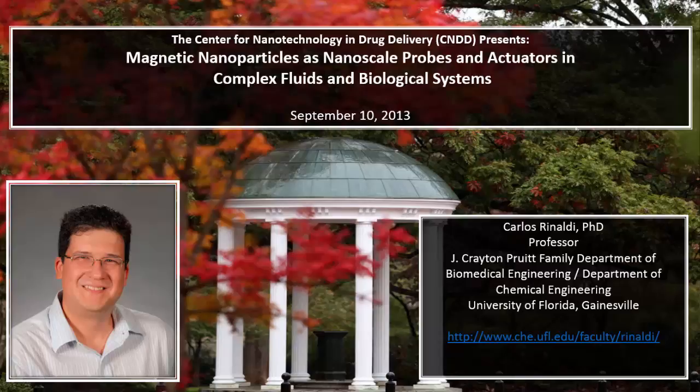You can make this quantitative, and this shows work that we've done, reported in Soft Matter, where we used oleic acid-coated cobalt ferrite particles. The nice thing about cobalt ferrite is that at room temperature, it responds to an oscillating magnetic field by physically rotating. We determined the hydrodynamic size distribution in a reference fluid, in this case hexane. We fit that to a log normal size distribution, and then we suspended the particles in a test fluid, in this case mineral oil, which we bought at a local pharmacy. And the idea was to see if we can determine the viscosity using this technique.